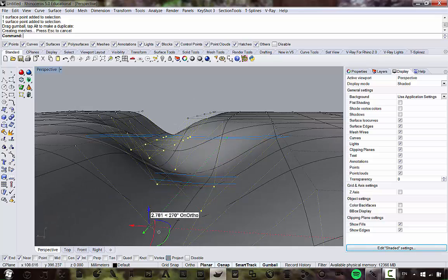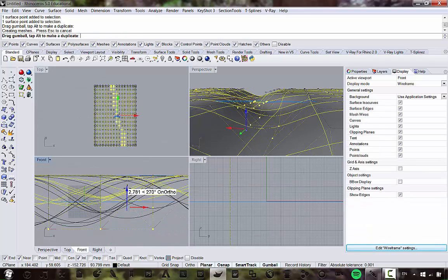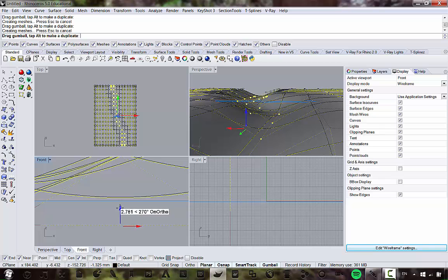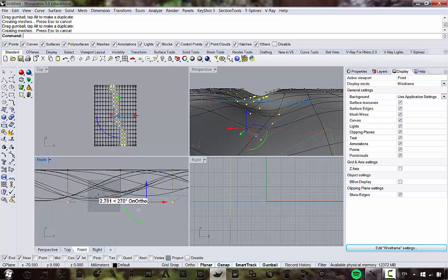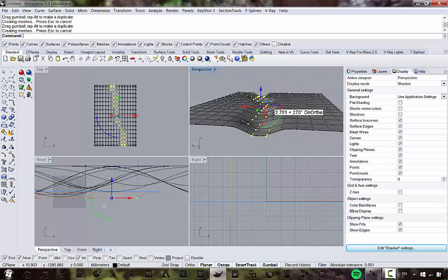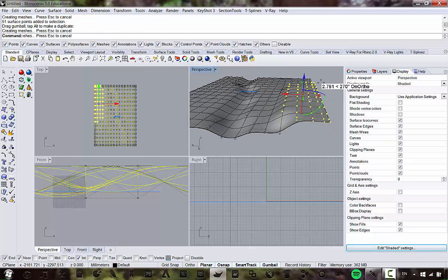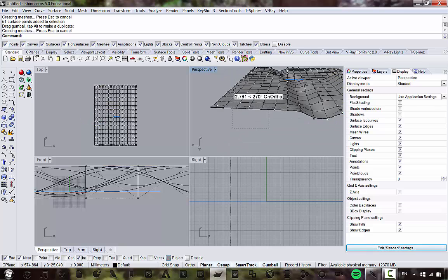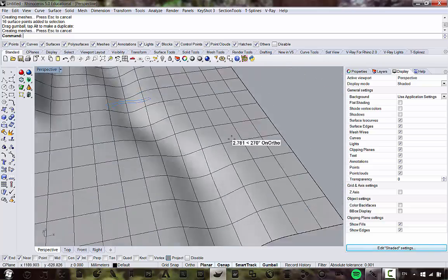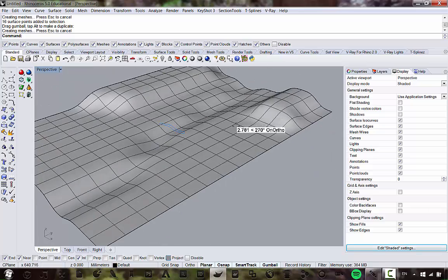So essentially we'll lower these down to, let's say, just above the base of our bridge right here, because we're going to trim some things away. You'll see that here's our base right here. So we're just going to lower it down to this point. So that looks good. If you wanted to edit the topography more, you could make a hill up here, or whatever you feel like doing. In this case, this is our little river down here. Does anyone have any questions about doing that and editing surfaces with control points?